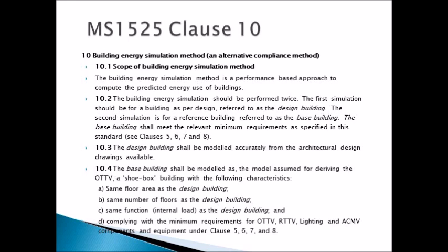So let's say you are designing a hospital, the base building also should perform the function of a hospital. And the base building should comply with the minimum requirements for OTTV, RTTV, lighting, and all those components and equipment stated under clauses 5, 6, 7, and 8 earlier. So the hypothetical base building, the shoebox building, must meet the prescriptive requirements of the document. Okay.